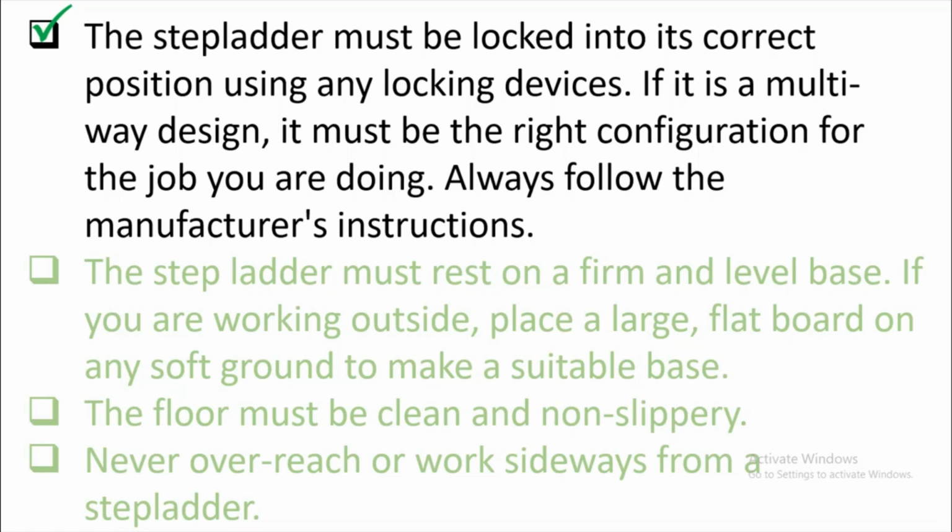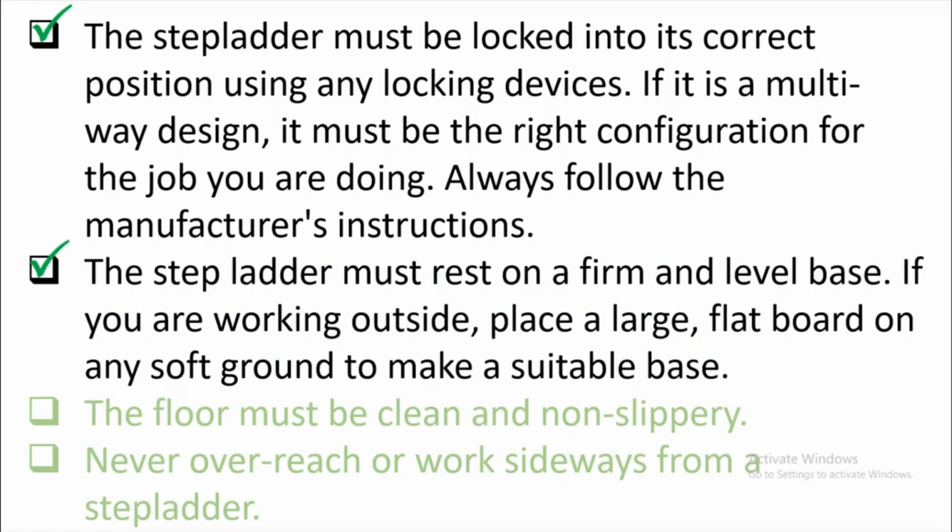Always follow the manufacturer's manual. It's very important. Verify how to use such a step ladder so that you can avoid accidents. Step ladder must rest on a firm and level base. If you are working outside, place a large flat board or any soft ground to make a suitable base.